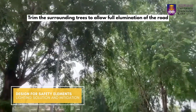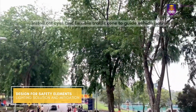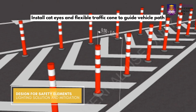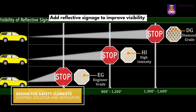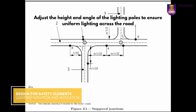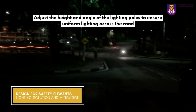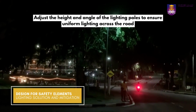Trim surrounding trees near lighting poles to allow full illumination of the road. Install cat eyes and flexible traffic cones to guide vehicle paths and warn drivers of pedestrian zones. Add reflective signage at key locations to improve visibility. Readjust the height and angle of lighting poles to comply with JKR standards and ensure uniform lighting across the road. This action will improve visibility at night, enhance pedestrian safety, and bring the road facility back in line with national safety standards.